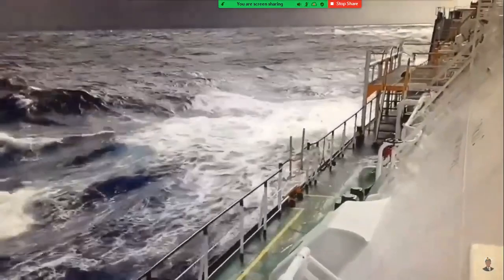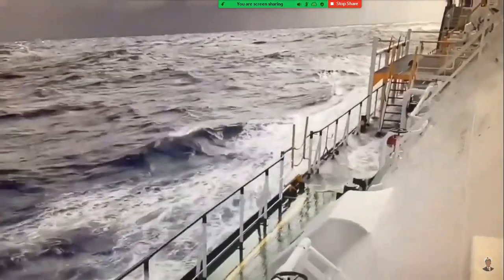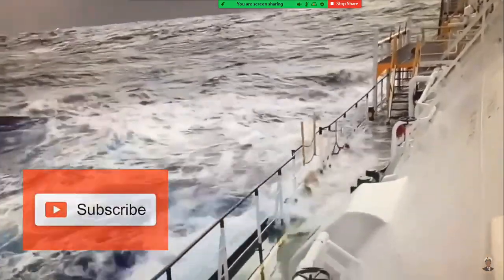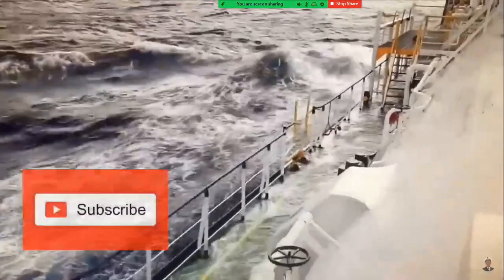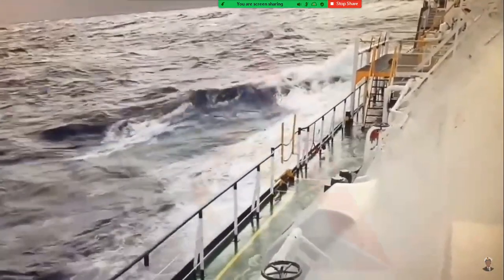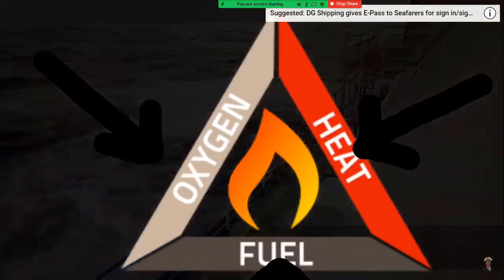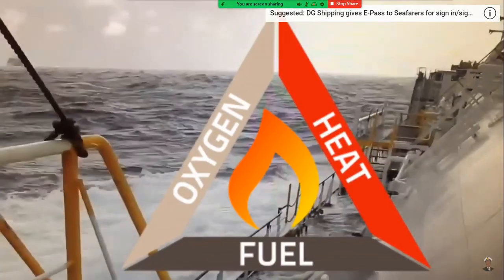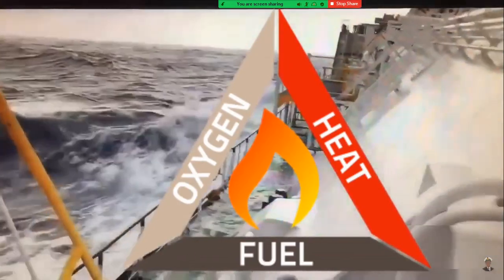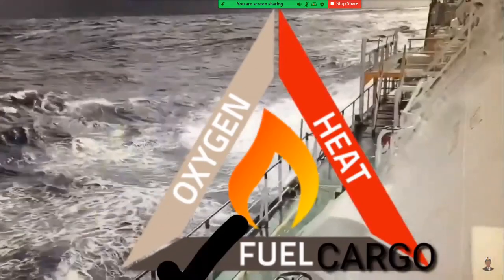Cargo operation in tanks involves a lot of pre-planning and discussion to prevent any kind of accident or mishap. Proper procedures are followed during loading, unloading, tank cleaning and even man-entry time. It is known that for any fire to start, it requires a minimum presence of three components, that is air, fuel and a source of heat in the correct proportion, which are the three major sides of the fire triangle, as we are already familiar with. In a cargo tank or vessel, cargo can play the role of fuel and complete one side of the fire triangle.